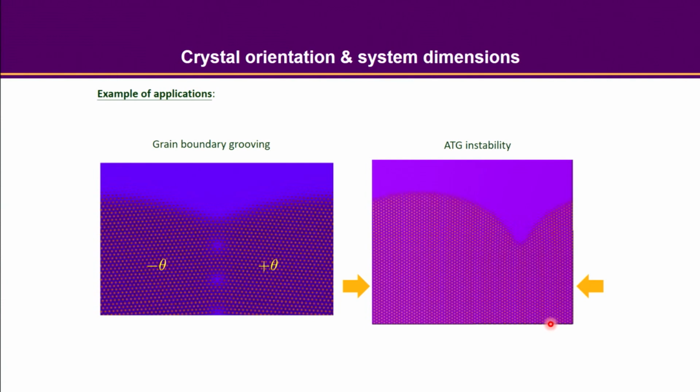One way to implement the stress is to bring your stress-free solid and apply a strain on it. One simple way to do it is to first set up the proper Lx, Ly in your system, so everything is stress-free. Then you assign a proper density profile as your initial condition. But when you actually run the simulation, Lx is not the proper Lx you gave at the very beginning. It is just 99% of the value you assigned.